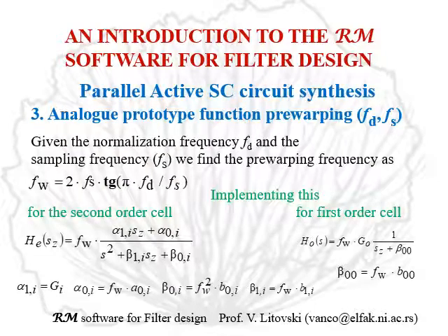Now, as already mentioned earlier, we start with the analog or S-domain transfer function, but to get the Z-domain transfer function, we implement the bilinear transform, and of course, before that, we are performing prewarping in order to compensate for the nonlinear distortions which are introduced by the bilinear transform.